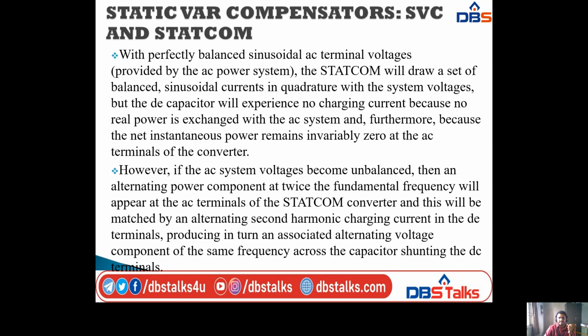The DC capacitor will experience no charging current because no real power is exchanged with the AC system, and because the net instantaneous power remains invariably zero at the AC terminals of the converter.